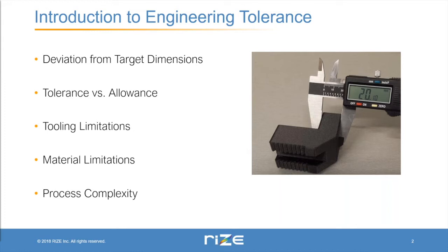There can sometimes be a bit of ambiguity among similar terms, things like tolerance, error, relief, allowance. So I wanted to make the distinction that tolerance is how far you are from the target, whereas something like allowance would be the amount of space that's left, the amount that you deliberately reduce from a given target in order to leave space for a joint, for example.